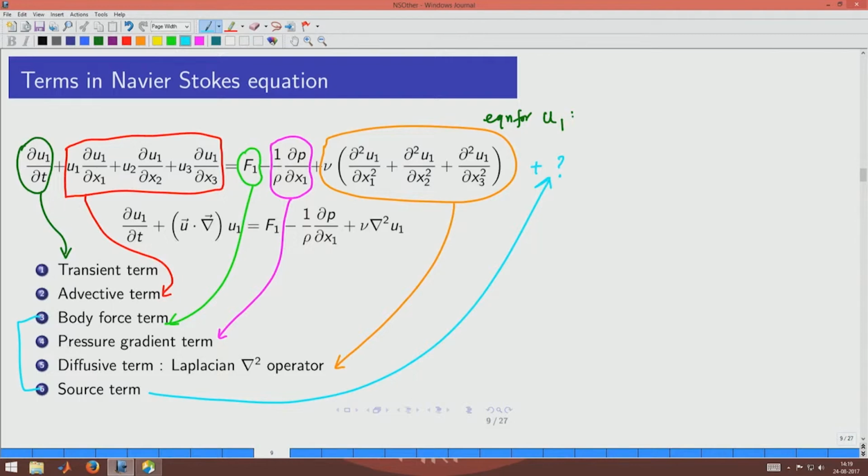And if you look at this equation in the vectorial form, you see there is a material derivative term here, a grad term here, and a Laplacian term here. Having derived the Navier Stokes equation, if you want to see how it looks in other coordinate systems, perhaps we can just look up these operators in those coordinate systems, substitute and proceed.